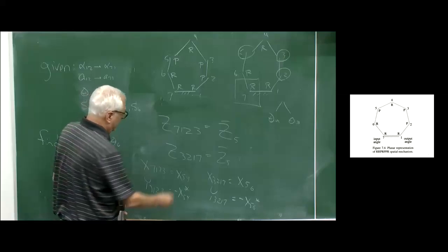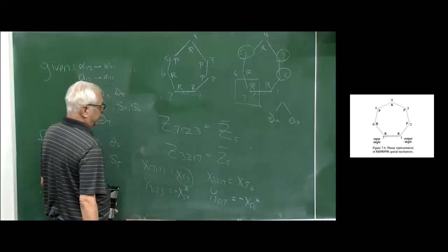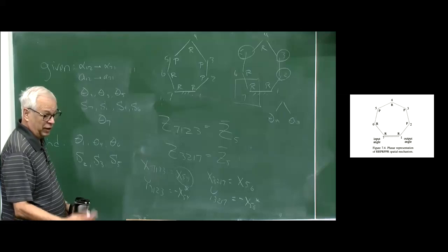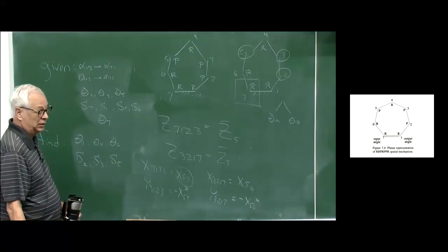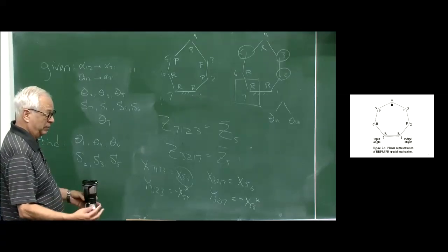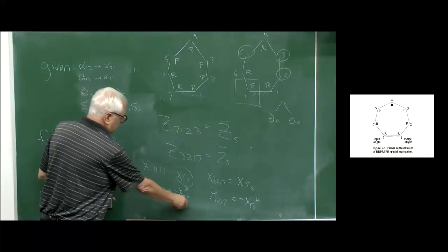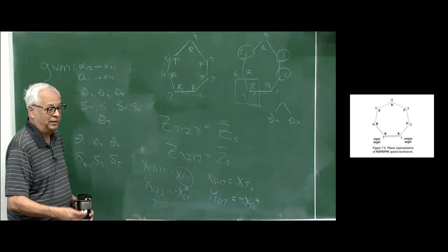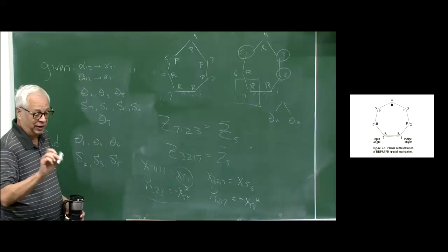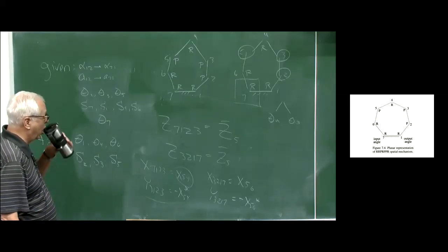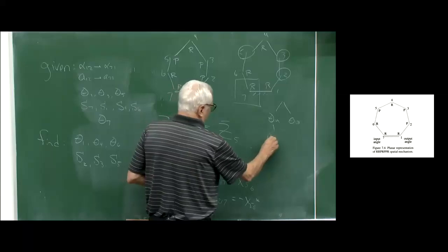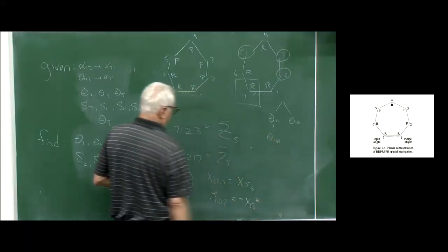And again, when you expand this definition, we're going to get the sine and cosine of theta 4 pop out. We evaluate basically with these two equations, right? We get two equations, two unknowns. I'm getting lazier and lazier. I'm going to keep the chalk budget low today and not write as much. From those two equations, though, we will be able to get the corresponding value for theta 4a.